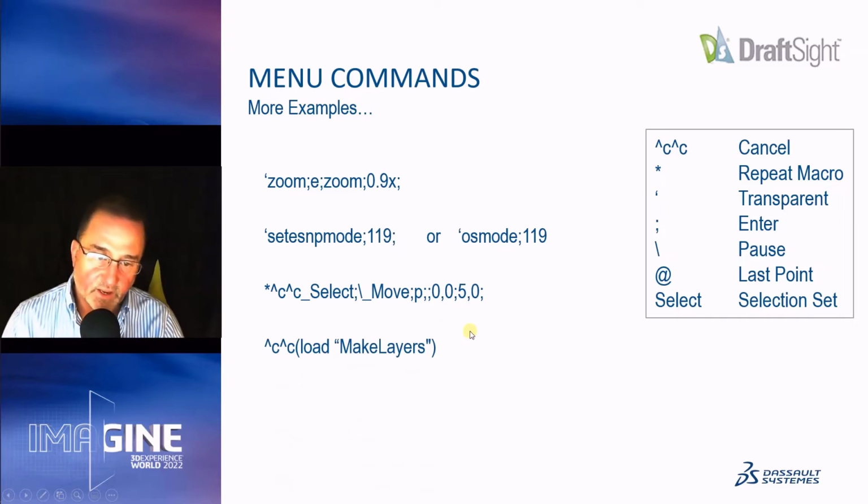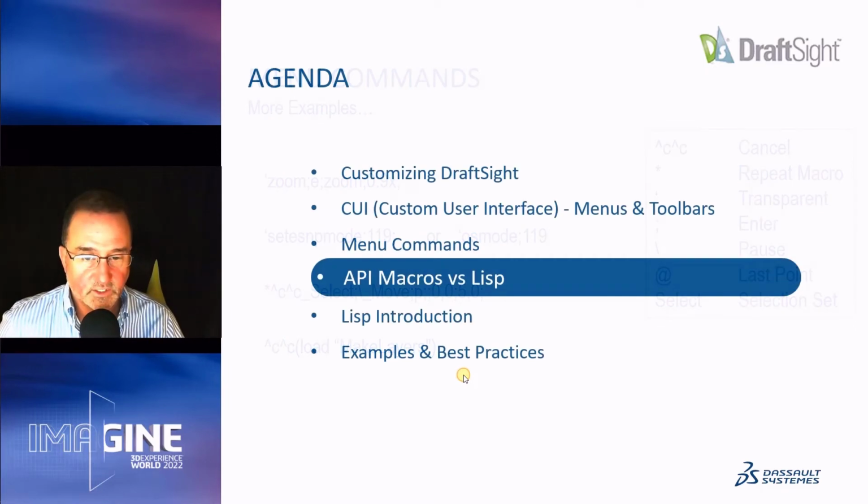And then if I have, let's say, a program that's a Lisp routine that I want to load, simply all we have to do is _C, open parenthesis, load the name of the Lisp routine, close quote, and close parenthesis, and we can load that Lisp routine.